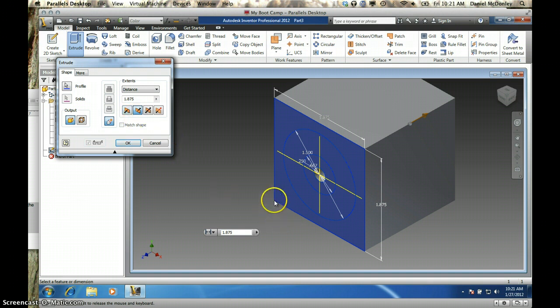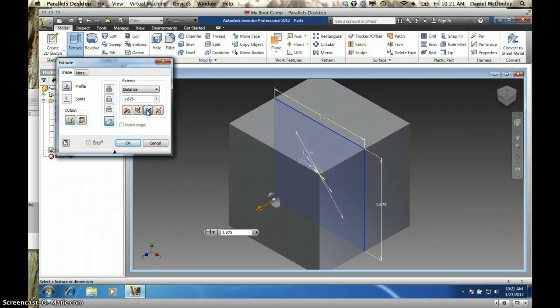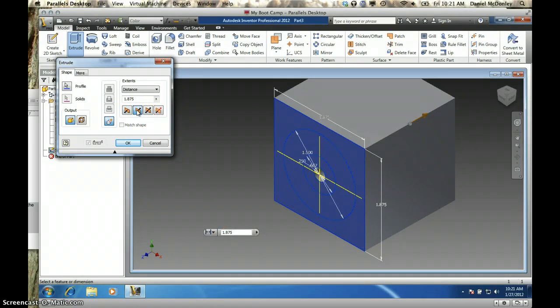You can see that the y-axis is this way, the x-axis is this way, and z-axis that way. I'm going -z, and it's going to end up being positive y and x. The reason I'm doing that is because that's going to be the point of origin I cut on the CNC mill. So it's nice that I just do it in the same brain. But you can do it however you want. You can actually make it in the middle, like this. You can create an offset so that it's one side or the other. But this is the way I'm going to start.